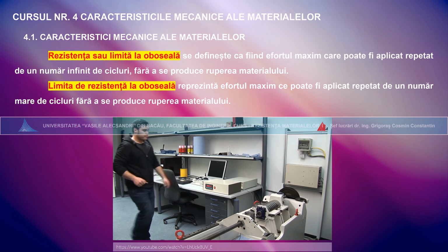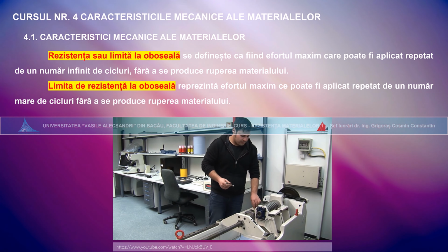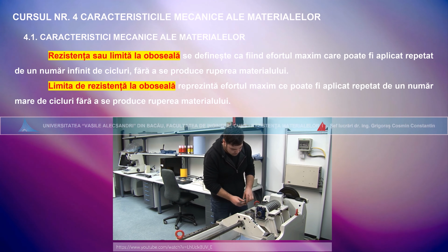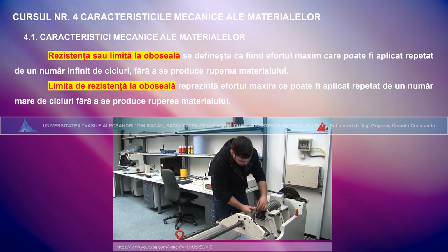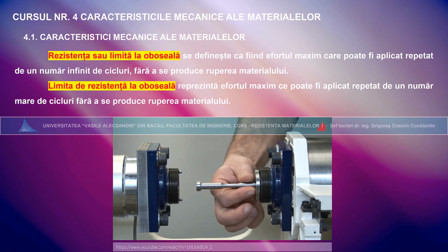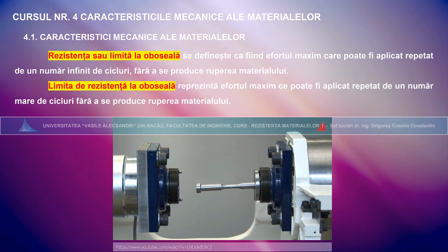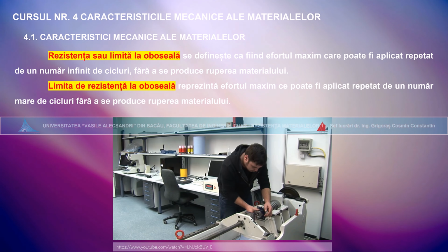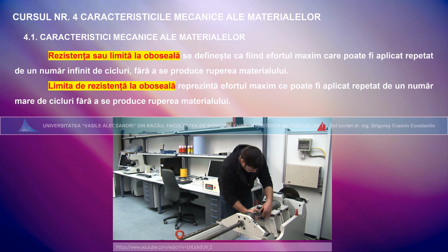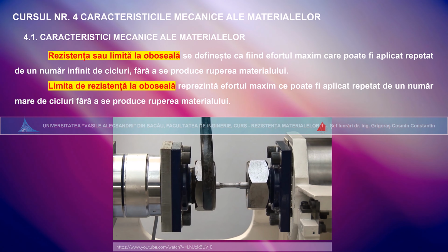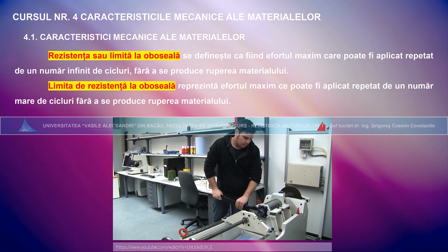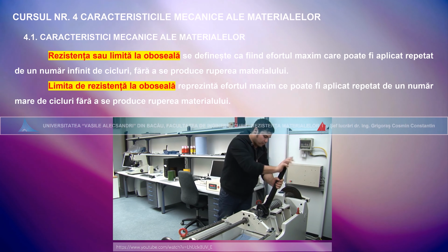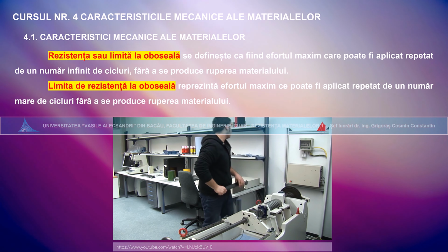Back in the lab, he has all specimens ready for use and picks out the first one. He mounts the specimen carefully and securely into the fatigue testing machine. Together with 2 half shells, he inserts one end of the specimen into the right specimen grip. With a union nut, he locks the right end of the specimen. Likewise, he mounts the left end of the specimen into the left specimen grip and tightens the nuts. The preparation is now complete.